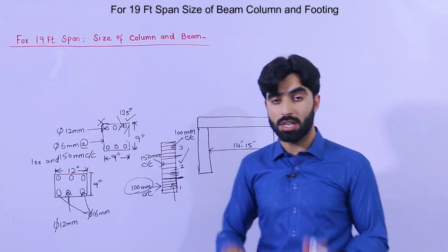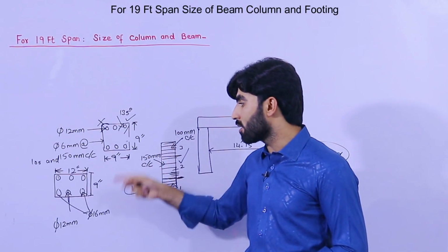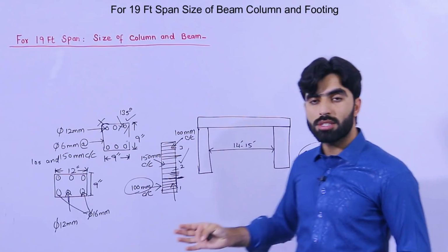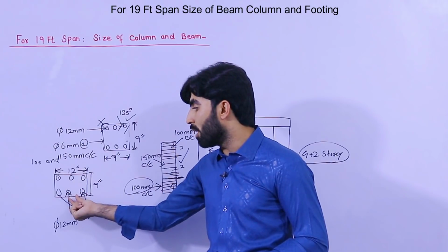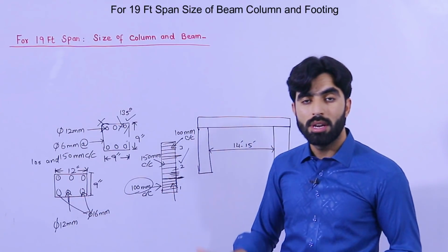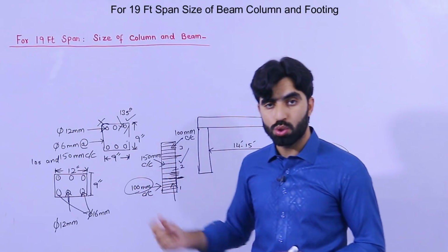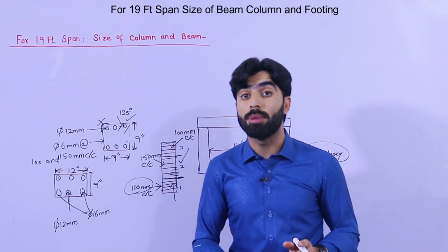If you don't have the structural design and you don't know about the structure load, etc., in that case the size of the column should be 12 by 9 inches, 6 steel rods, corner steel rods dia should be 16 millimeter, other 2 extra bars and side bars should be 12 mm, lateral tie spacing should be 100 to 150 mm, the hooks should be bent with 135 degree, and the dia of lateral tie should not be less than